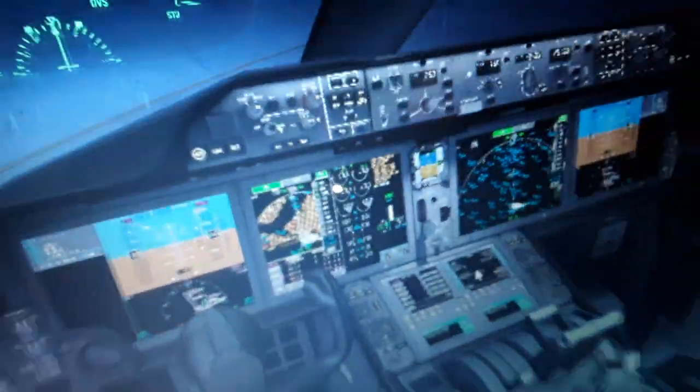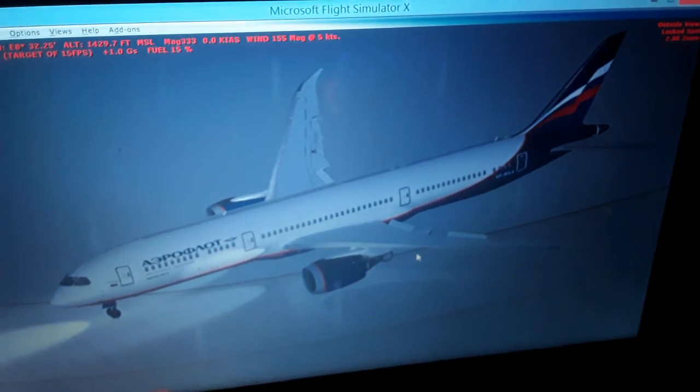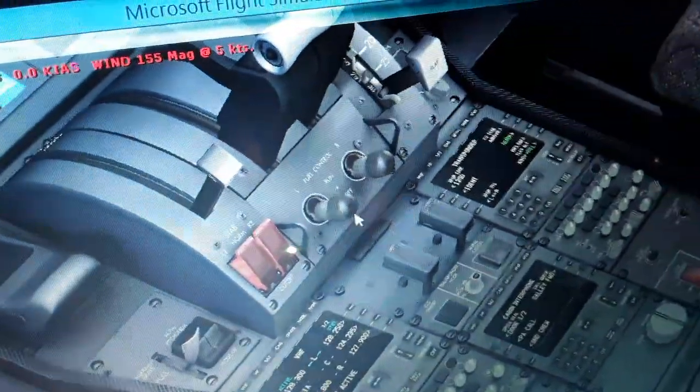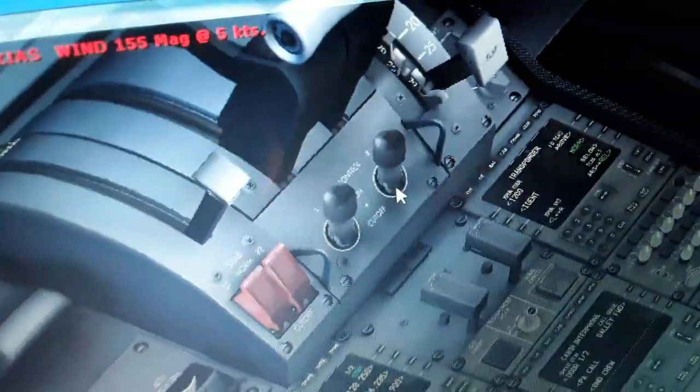We have only pressurization, we have no fuel yet. Above 30% we can set the fuel control over here in the on position, fuel flow, fuel valves, both on.